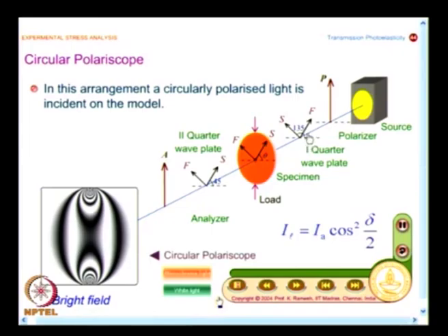And what people have found is, if I keep the quarter wave plates crossed, the error introduced because of mismatch of the quarter wave plate is minimal. I can show you the graph without proof, but this is a thumb rule, and that is how many conventional photoelastic analyses are carried out, and the same knowledge extends even in digital photoelasticity. So, now what we will do is go and look at how to analyze this mathematically.